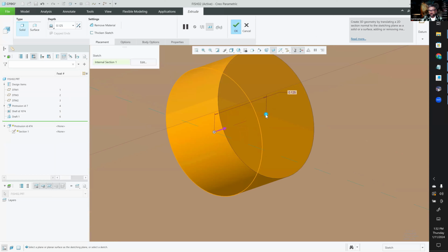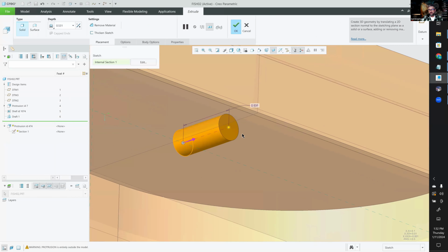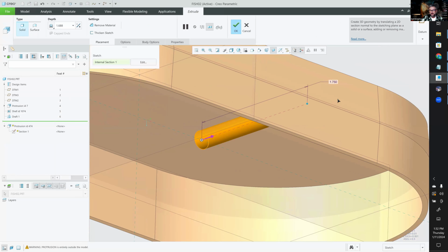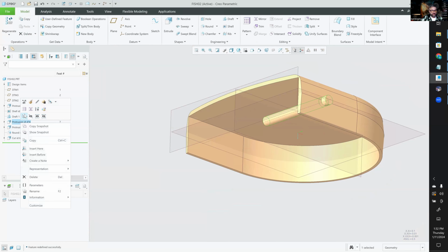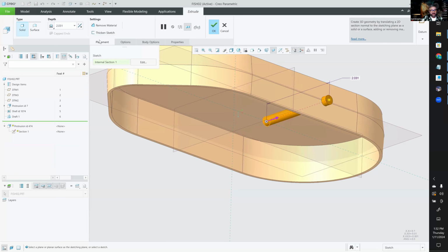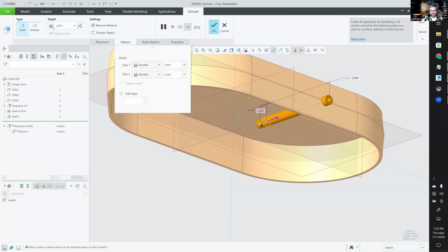So what I'm eager to show are a lot of cool new tricks from Creo 3 on. So there's my part. It's sticking out, but I don't want any of this geometry, right? So I'll edit definition on this part, and in the other direction, make it go a negative number, okay?